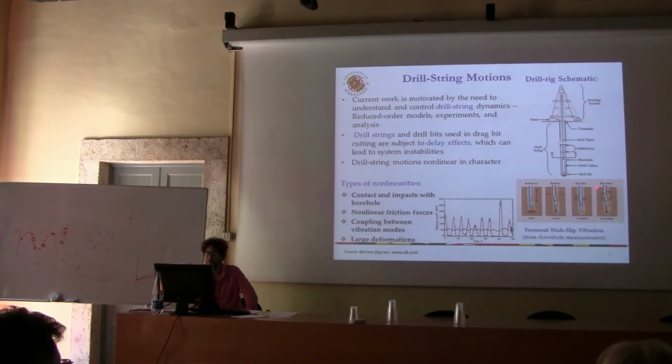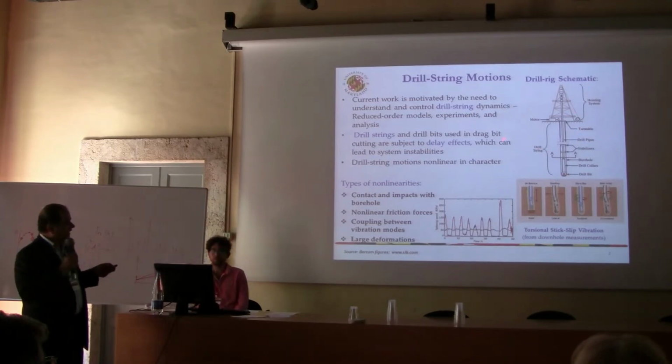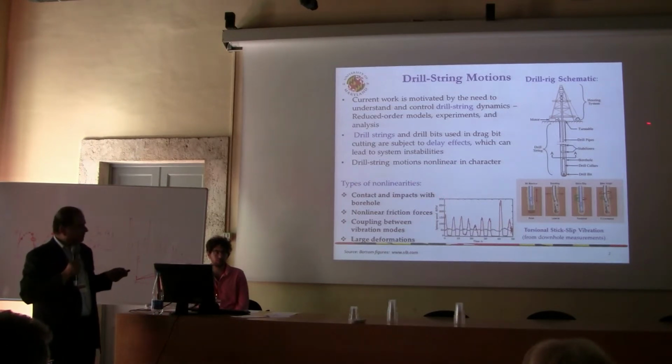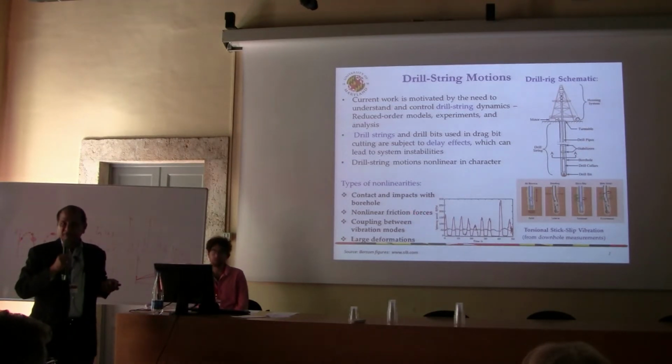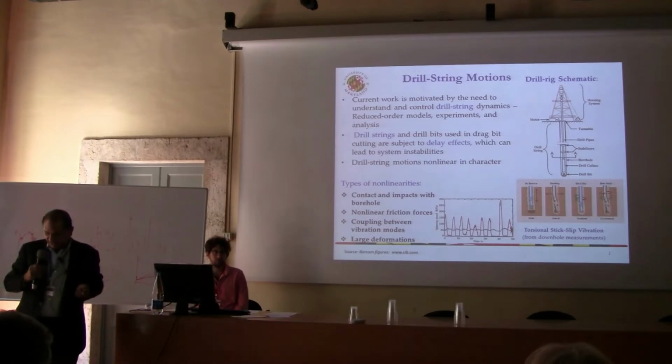And this, if you have any eccentricity in the drill string, given its length, it's quite possible that could induce some dynamics as well. So in terms of things to note, we do have delay effects since you have a cutting action, and also the drill string motion is nonlinear in character because you have contacts and impacts with the borehole, its outer shell, as well as the bottom. Nonlinear friction forces, you could have coupling between the different vibration modes depending on the frequencies that they have and the nonlinearities in the system. And of course, in this case, given the length of the system, you do have large deformations as well.